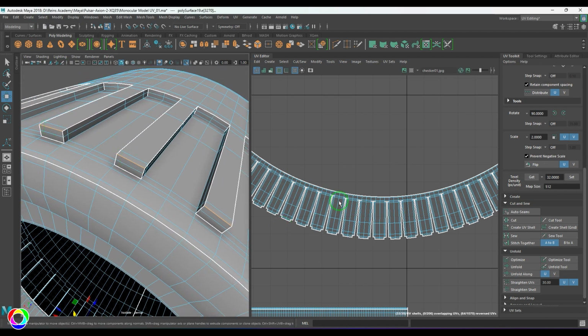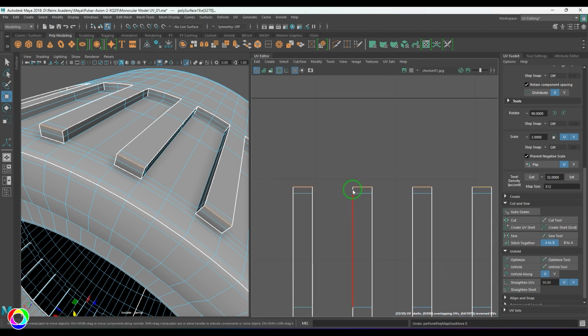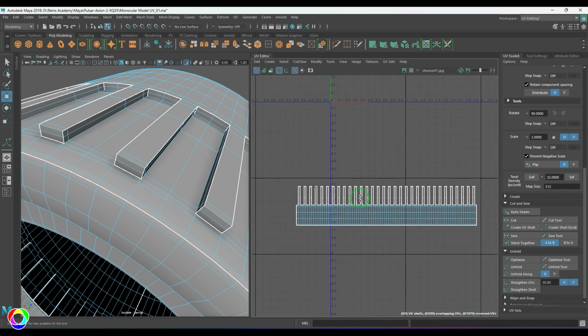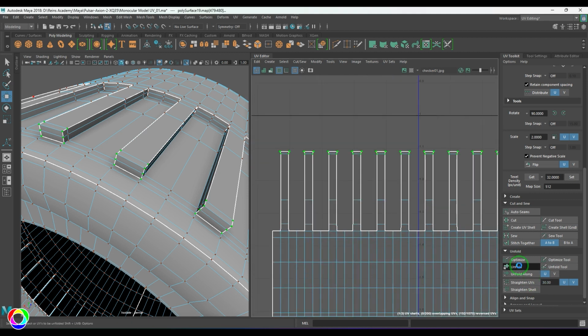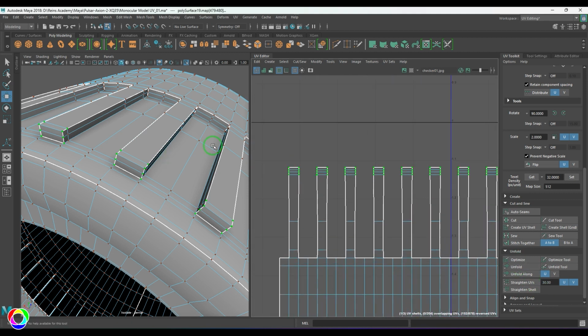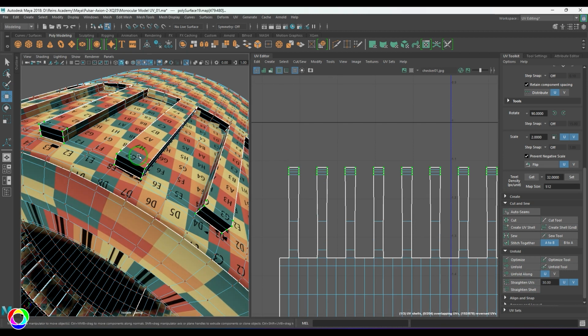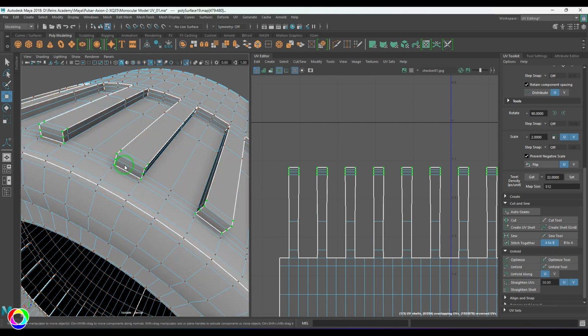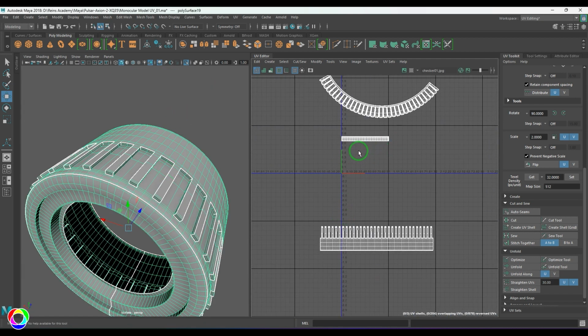So all lines are selected and move and sew. They all came here. You should be able to see that, right? Just select those UVs and then unfold. They are just opened up. Okay, that keeps a minimum number of shells.